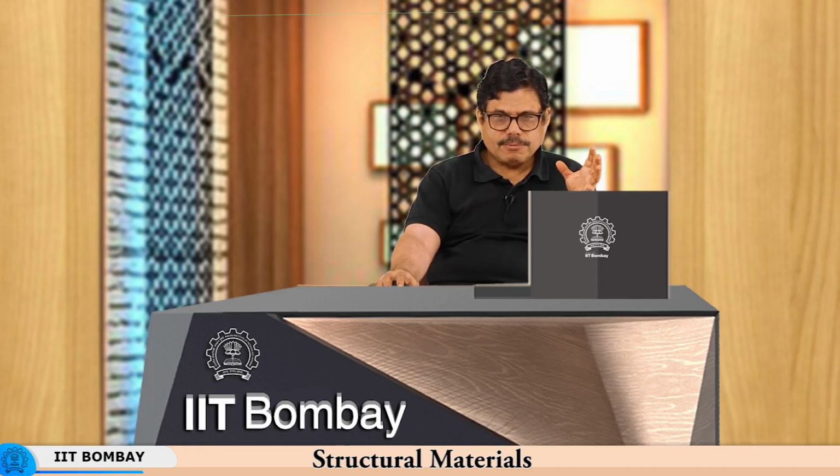That is what is called creep, which is a time, temperature, activation energy dependent phenomenon, particularly when metals are subjected to prolonged heating and loading. For instance, take boilers. Boilers are subjected to heating, maintained at a certain temperature for a prolonged period of time, and there is internal pressure acting on the material, sustained over the entire duration of operation. So, this subjects the material to creep, where the deformation depends upon time, the extent of duration of exposure, the temperature, and the corresponding material property, namely the activation energy.